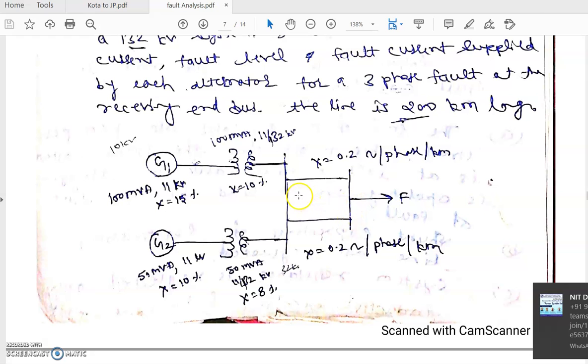If we want to solve it, and the values of G1 and G2 are the same, we can also see that this is grounded. So the G1 and G2 terminals are also grounded. So it becomes one complete circuit, and we can take G1 and G2 outside of that circuit, because if the value of the source is the same, the source can be redistributed according to circuit analysis concepts. So G1 and G2 become a single generator outside, 1 angle 0, and this system becomes parallel.